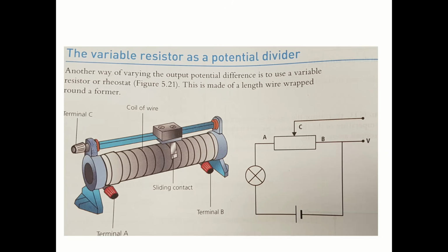Talk about rheostats then as well, because that little YouTube video has a section about using the rheostat in it. They've got a rheostat in the circuit connected with 2 connections and then with 3. And at this stage, it's worth really showing the students how this works. It's the 3-connection setup, because it's not always obvious the first time you do it. So it's worth taking a variable resistor like this in your hand and explaining exactly what's going on at this stage, I would say.